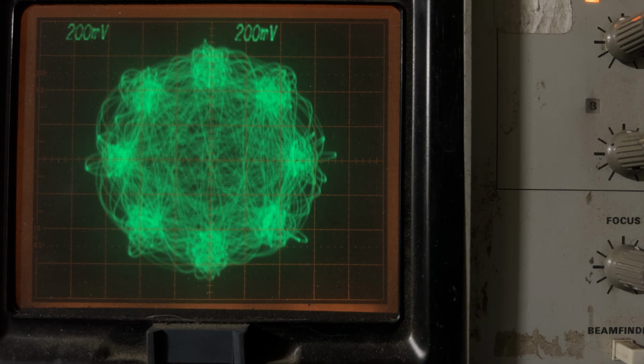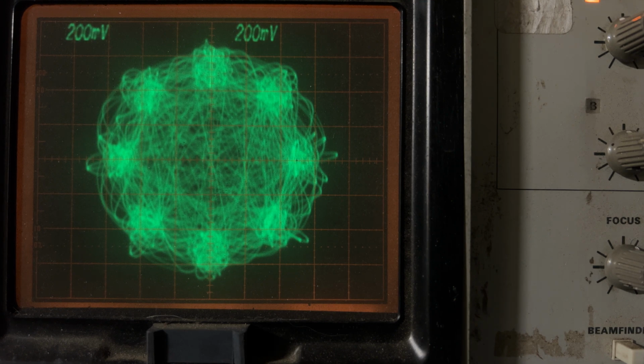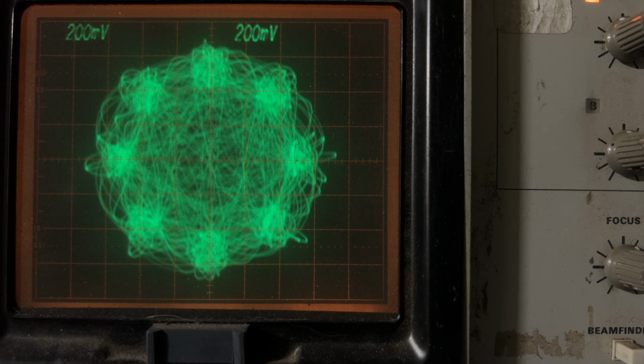So I'm looking at the output of the IQ mode of this generator on my Tektronix 7904A 500 megahertz mainframe, but I'm using 200 megahertz plugins on X and Y. I have the X axis on I, the Y axis on Q, and the symbol rate is 1 million symbols per second, because that's the default symbol rate for this generator, and every time you switch modes, it switches the symbol rate back to the default, which I find somewhat annoying, but that's what it does. But I'm doing this on the analog scope because some things just look better on analog oscilloscopes, and this is one of them.